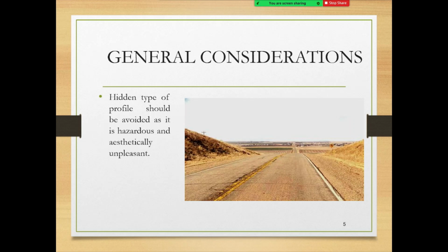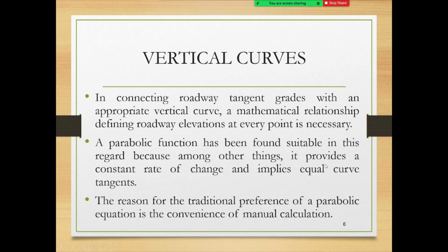Now in theme parks, have you seen a roller coaster? It is going up, going down, up and down like that. So it is called a roller coaster. So a road should not be designed as a roller coaster, or this is called a hidden dip. Okay, because you don't see that. It's called a hidden dip. A roller coaster vertical alignment or hidden dip, right?